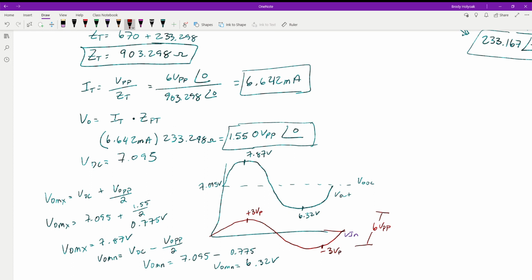And we know the timing of this, and then we can build our receiver circuit so that it's looking for the signal, but it's looking for it in a time. And if that time gets delayed, that means the beam's been broken and somebody's crossed through the system. Just different applications, because sometimes it's more efficient to use a pulse than it is just a constant signal, and looking for that. And so, we'll get over the 7 volts, the sensor turns on.